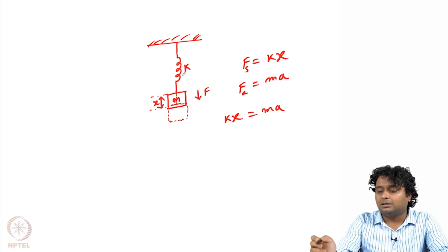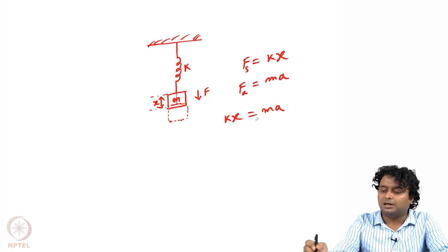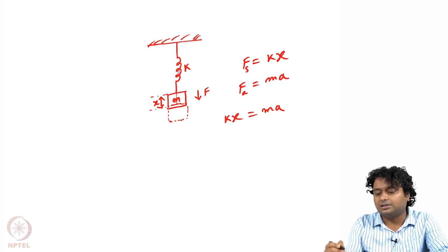So how can we measure? This is the same phenomenon we will use, which we have been discussing from module 1 itself, right, that if we apply some amount of force, then there is this deflection, and we can measure the deflection, and accordingly we can measure how much the force or the acceleration is. So here also this is the deflection of the spring. In our case, while we are using some kind of sensor, this deflection will be of that particular membrane or cantilever, and accordingly we can measure the acceleration.